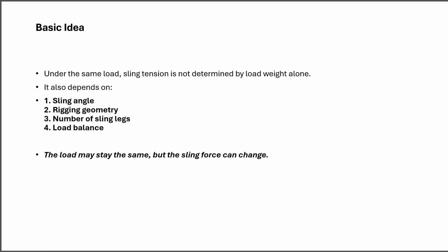It also depends on: 1. Sling angles, 2. Rigging geometry, 3. Number of sling legs, 4. Load balance. The load may stay the same, but the sling force can change.